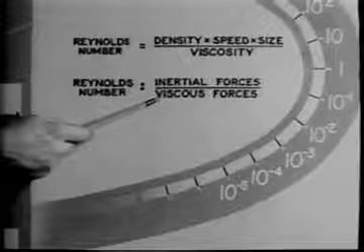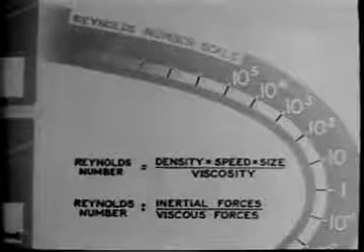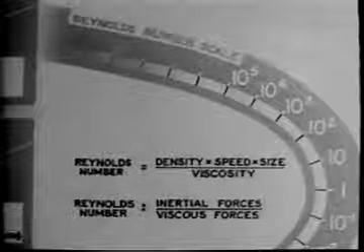the deformation. A very, very high Reynolds number, on the other hand, means that the viscous forces are so small compared with the inertial forces that the viscous forces may be neglected. We then have a balance between the pressure force pushing the fluid and the inertial resistance to acceleration. To summarize, very, very low Reynolds number means highly viscous behavior. Very, very high Reynolds number means only slightly viscous behavior.